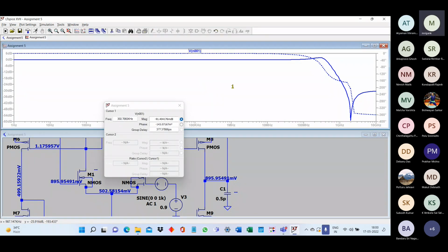Okay, so fine. We can see overall the effect, and whatever you have been asked to do, we have done it over here. We have first of all calculated the gain margin and phase margin for the given condition. We have looked at the error also. Then we tried to increase the gain. Of course, we have not been able to increase the gain by a factor of 10. If you want to do it, you can do that. Right now, the target given to you was that you reduce the error by a factor of 10.